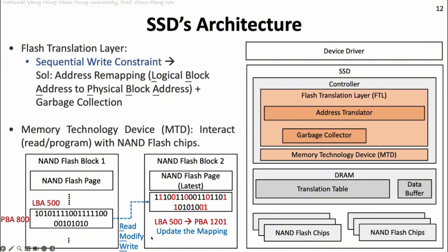So no applications know what's going on inside the SSD. The only thing they know is they can use the same LBA to do any operation. They can directly update this LBA, and they can still get the right data, because the SSD FTL will help with remapping the pages.